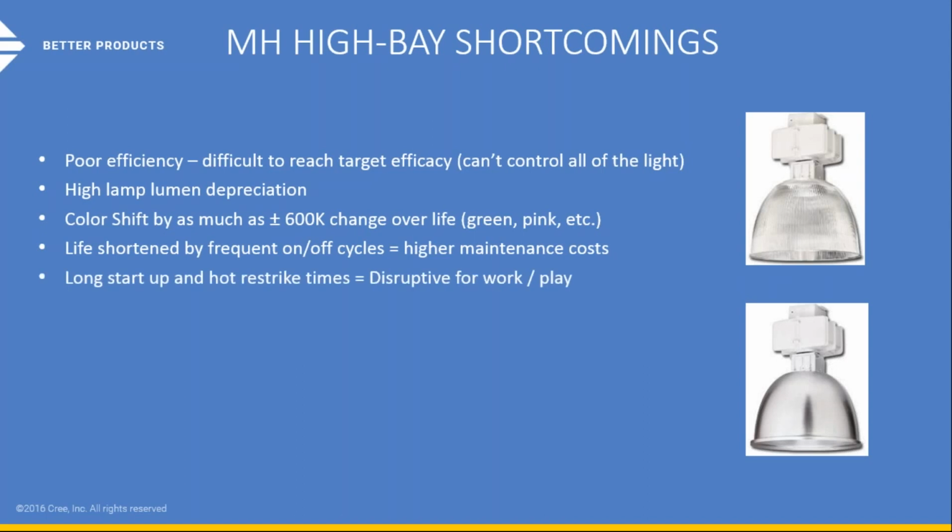Startup and restrike times. There are many examples here that we talk about. So power outages. As Ann mentioned, you guys are experiencing a storm. There might be situations where the lights will shut down and turn back on. Metal halides have a really difficult time of regenerating their power up to the levels that it needs in order to provide the light. If it takes a little time to do that, your workers or your processes are basically shut down for a period of time.